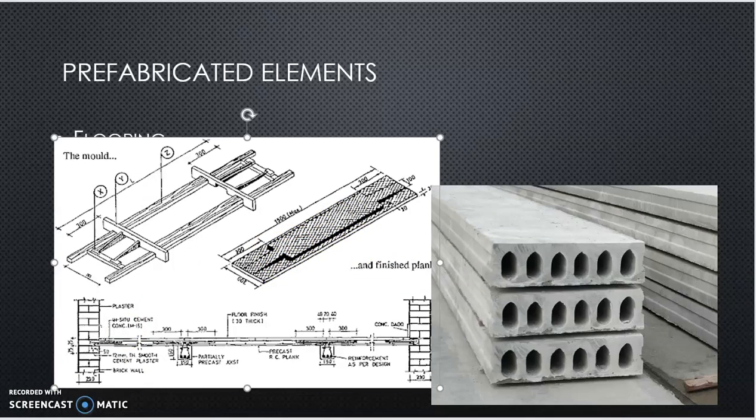So what is usually done is you keep these panels next to each other and then you start pouring concrete on the lower part. So all this part will have concrete. You will keep these adjacent to each other, and on this part there will be concrete and there will be some nominal steel also inside. I can't enlarge this.